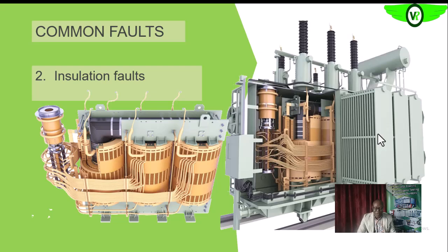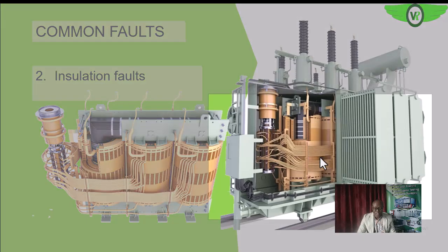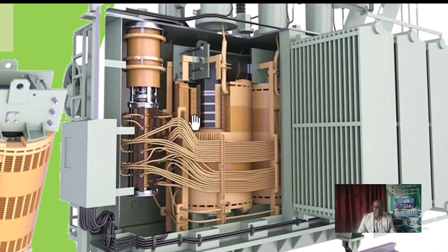For each of these sets, we have two different windings, primary and secondary windings. Like we said before, the primary and secondary windings are separated. As you can see, they don't have any connection with each other. The winding closest to the core is also separated from the core and does not have any business with the core. The only business that the primary and secondary winding have is at the connection point, at the start point or data point, outside. That is an electrical connection, no physical connection.